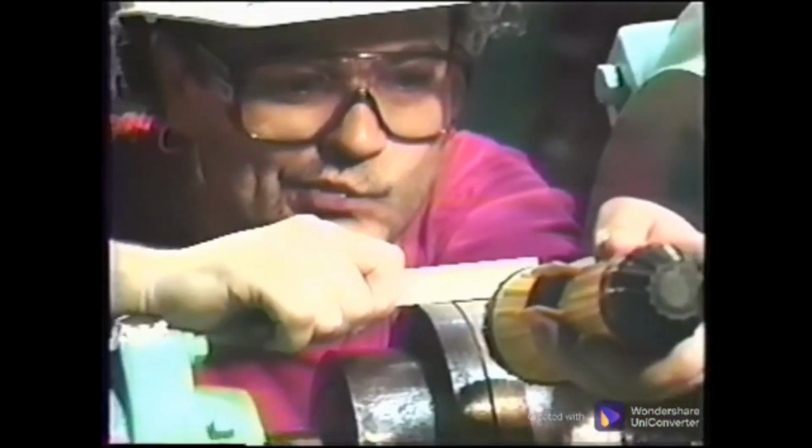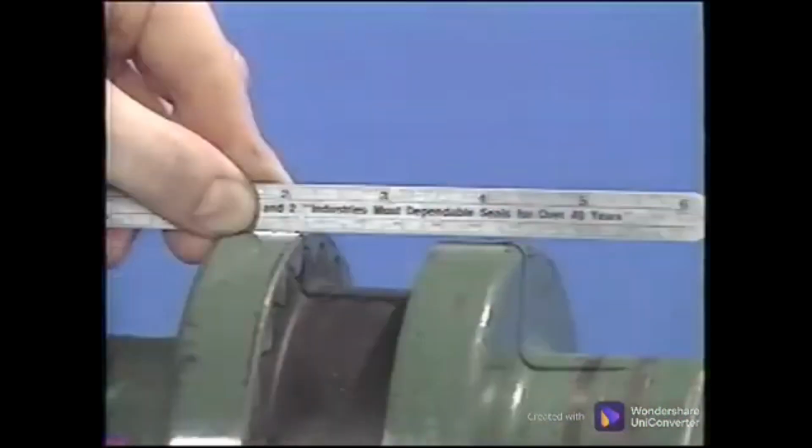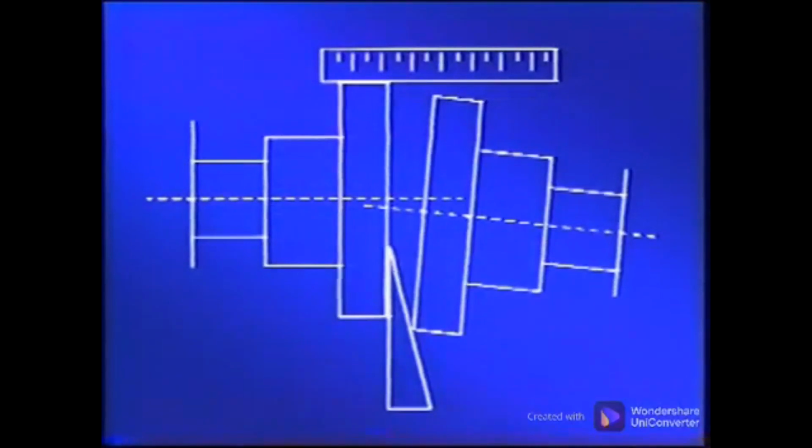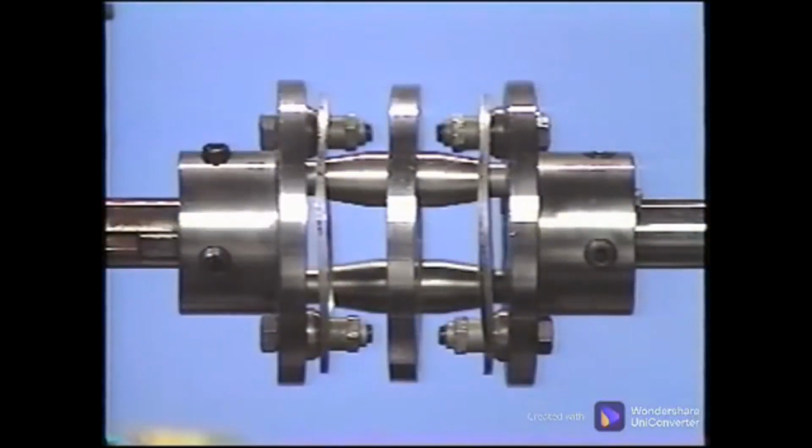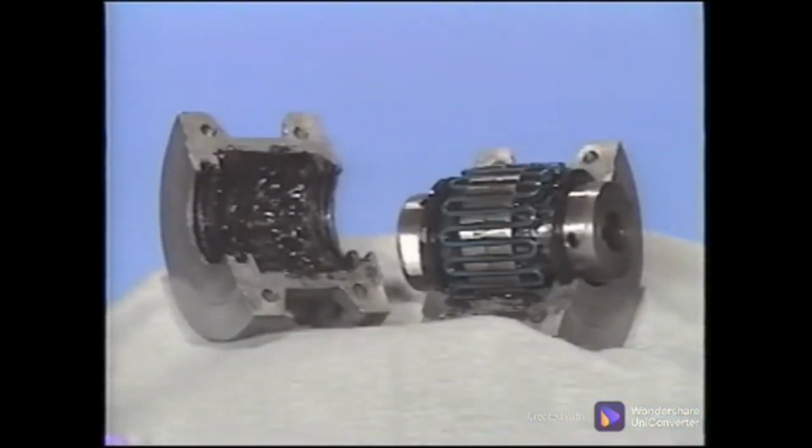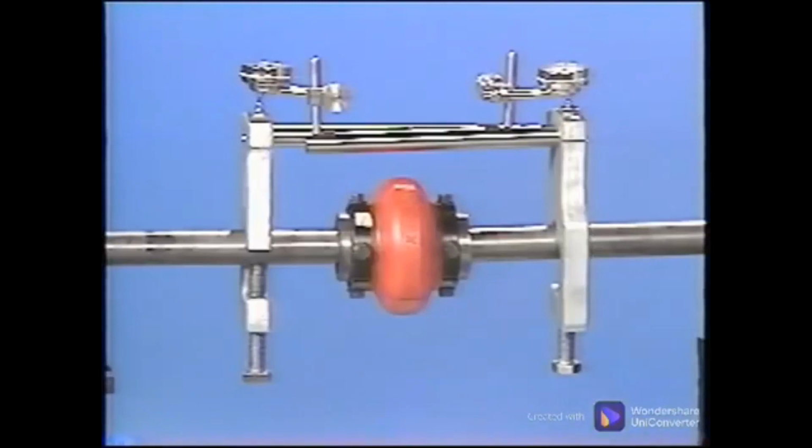The straight edge and flashlight method was only intended for a rough alignment during installation and is the least accurate method of alignment. The straight edge is used for the offset misalignment and a taper wedge or feeler gauge for the angular position of the shaft. However, it can only work on certain couplings, and because it does not require special tools, it is often used as the only alignment step before returning a machine to service.